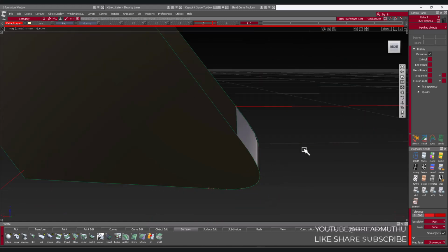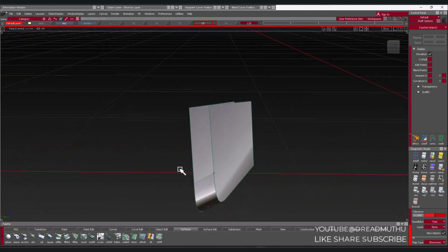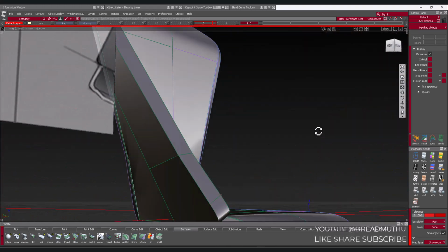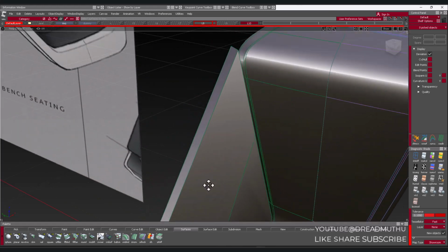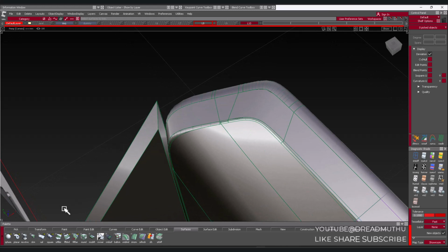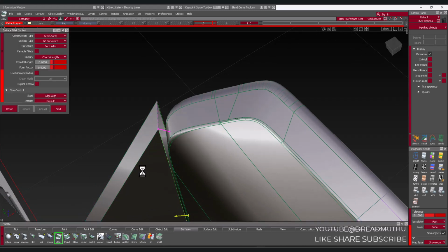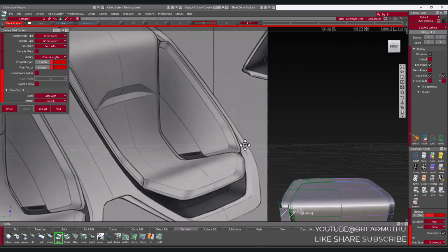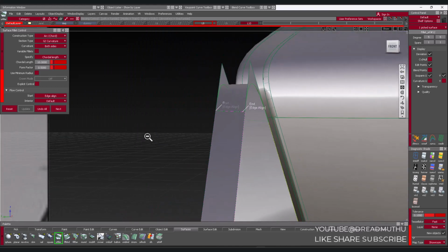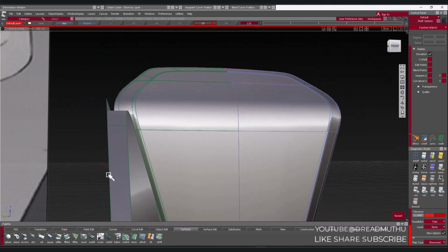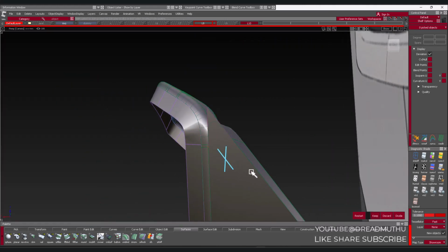Okay, then we will do this first, and then we'll go for the center one. Surface fillet again. Let's look, okay, intersect this and this with this. Let's see, we can trim this one. I don't think we can trim this one. Let's try. No, cannot. Let's project this. Also project this, trim. Yes. All right.